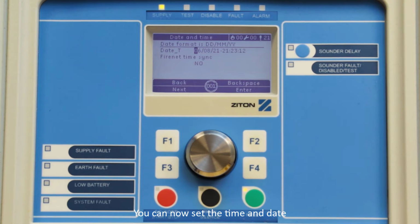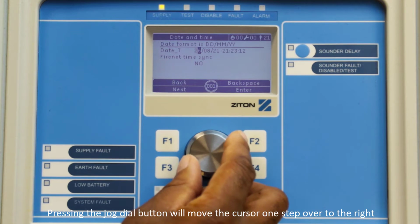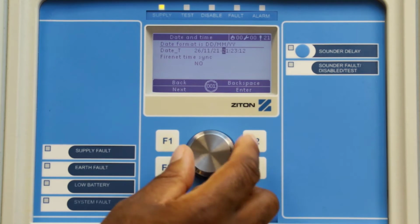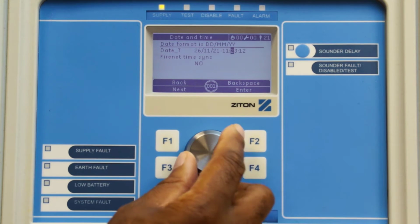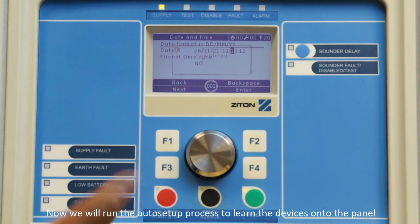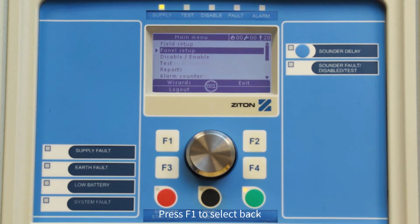You can now set the time and date. Pressing the jog dial button will move the cursor one step over to the right. Once you have finished setting the time and date, simply press F4 to select Enter. Then press F1 to select Back. Now we will run the auto setup process to learn the devices onto the panel. Press F1 to select Back.